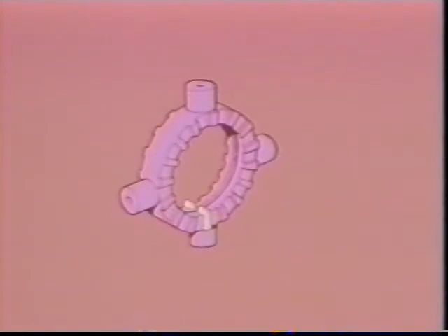The basic design is the same. The ring gear is bolted to the differential housing and fits together with the pinion drive gear. The cross assembly is clamped into the housing. There is a key on the inside diameter of the cross assembly. It looks like a long tooth.